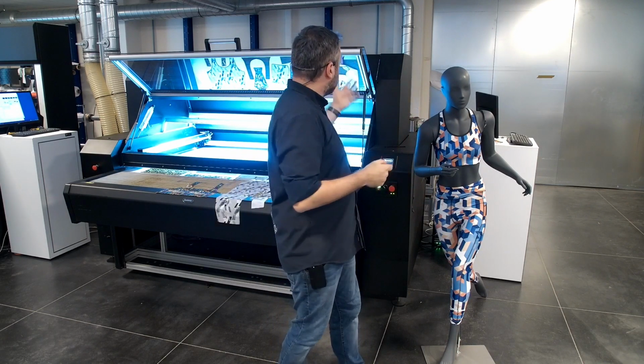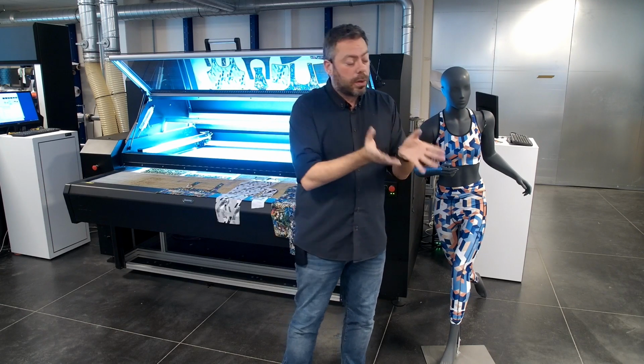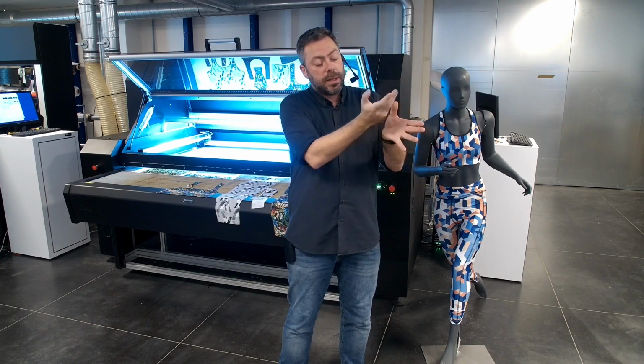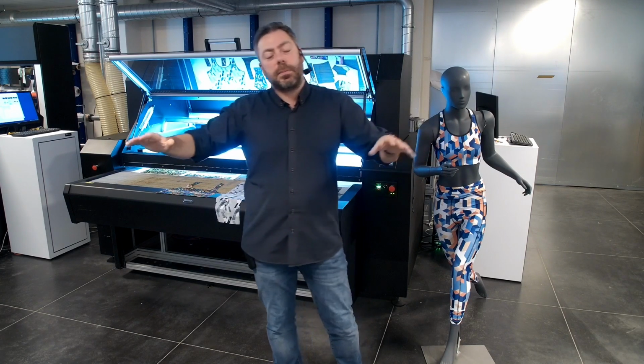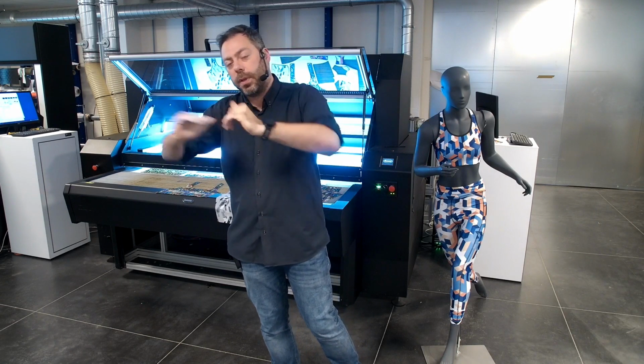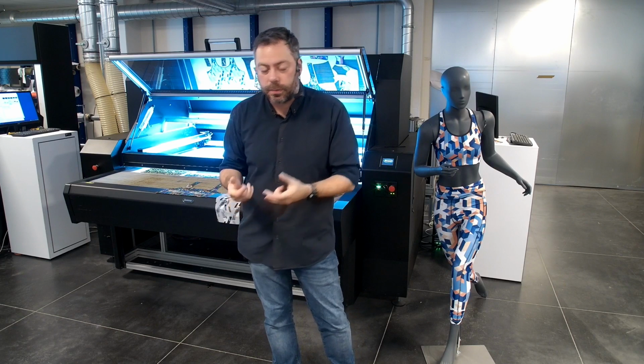Another thing that is difficult to show is that our de-reeling system also generates no tension on the fabric. If you look at our de-reeling system, generally there will be a loop running from the de-reeling system, and it will relax that media before it starts to be cut or before it starts to be transported by the machine. So there is a high focus on removing any stretch or any stress on that material.